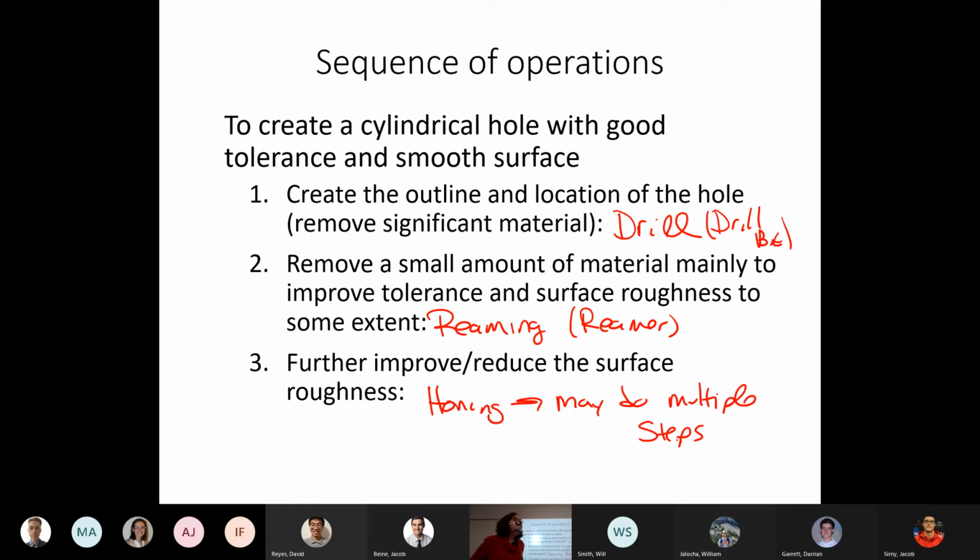And for a pump shaft, you really want some toughness. So what our operation was, is we had a cylindrical sleeve that was made out of the corrosion-resistant yet slightly brittle material. And we would attach that to a shaft that was made out of a carbon steel, maybe a little bit of alloy content in there, that had greater toughness.